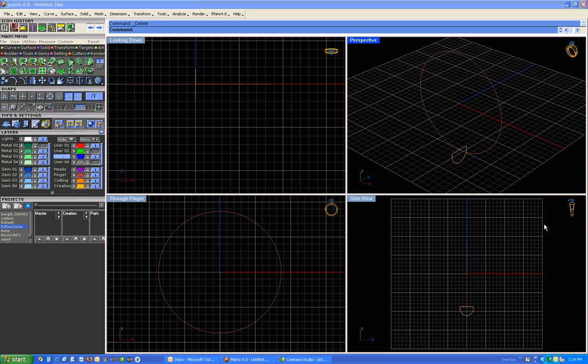Any engraving you want to do on the inside of the ring must be done by Boolean difference. This is covered elsewhere. Your best friends for getting curves onto the outer surfaces of rings and other models will be Create UV Curve and Apply UV Curve from the Curves menu.